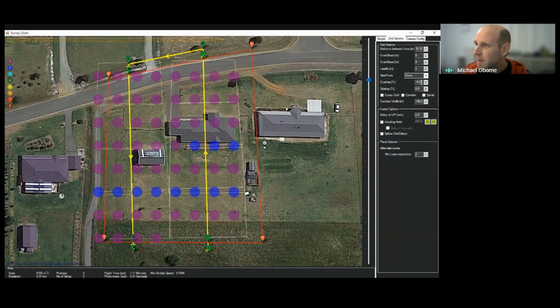So normally, the one thing you'll notice here as well is that you actually don't get overlap here. Now the reason for this is because the ground actually goes up. So this comes back to that ground elevation thing I was talking about before. Just from looking at this, I can tell down here is 36 meters at the bottom, and towards the top it must get higher, and that must be close to where the 42 meters is, because we're getting closer to the ground. The amount of ground the camera lens sees is actually less.